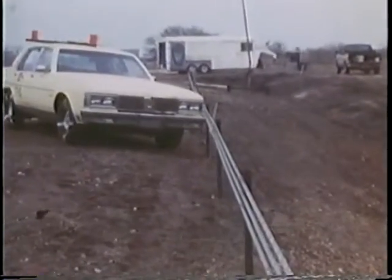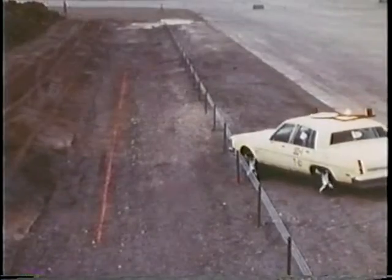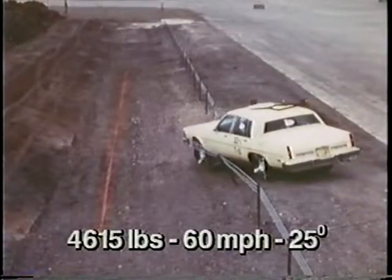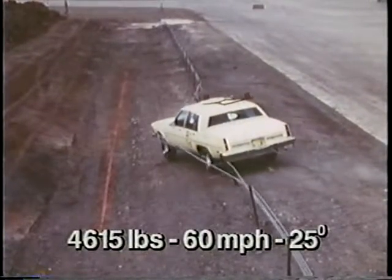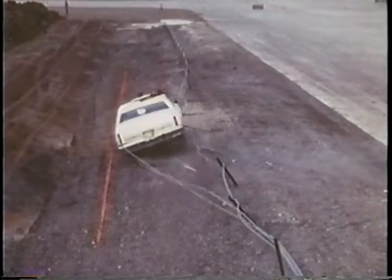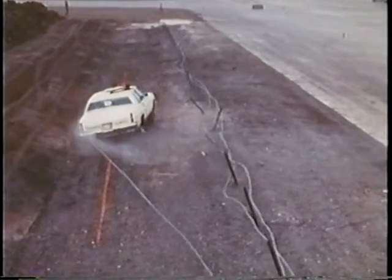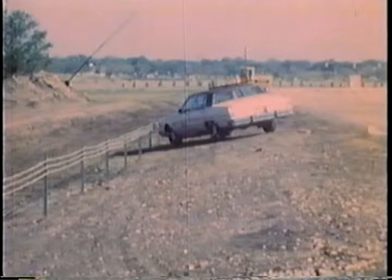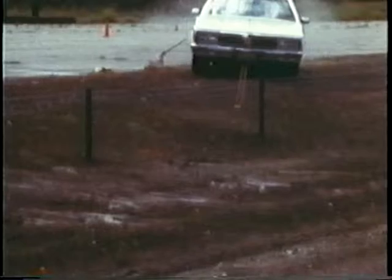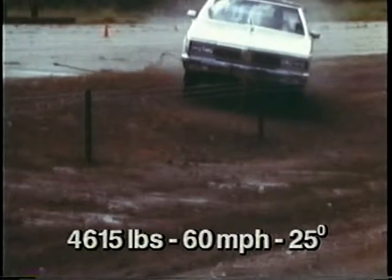The location of the guardrail on slopes is an important design consideration. If the guardrail is located on the slope but too close to the edge of the pavement, the cables may contact the vehicle below the front bumper, allowing the car to ride over the cables and penetrate the barrier. If the guardrail is placed at least 18 feet away from the pavement, the vehicle has more time to stabilize before it strikes the cables.